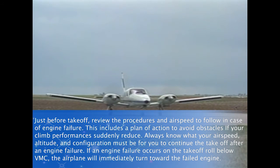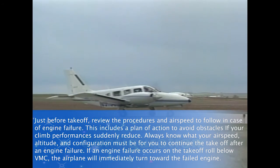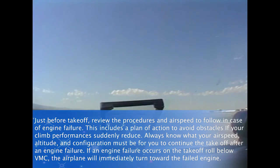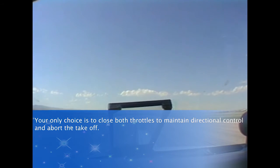Always know what your airspeed, altitude, and configuration must be for you to continue the takeoff after an engine failure. If an engine failure occurs on the takeoff roll below VMC, the airplane will immediately turn toward the failed engine. Your only choice is to close both throttles to maintain directional control and abort the takeoff.